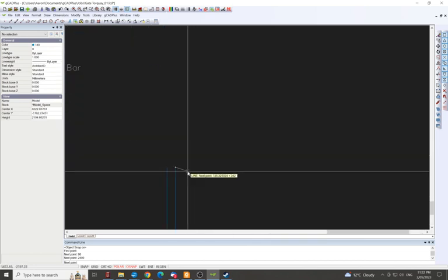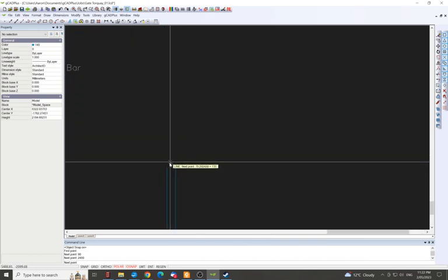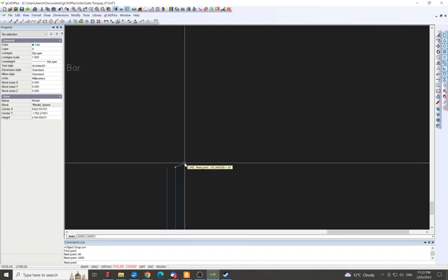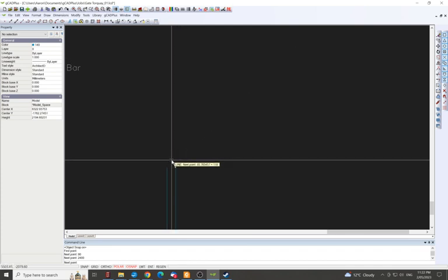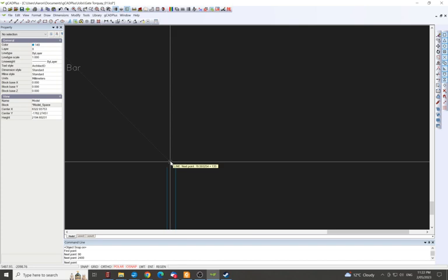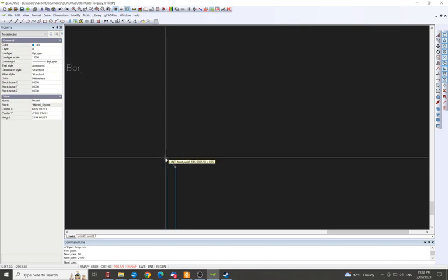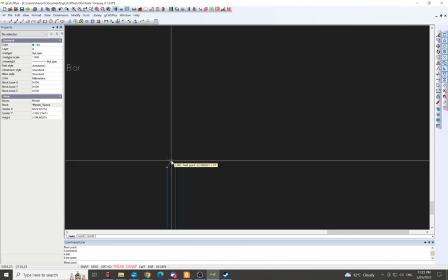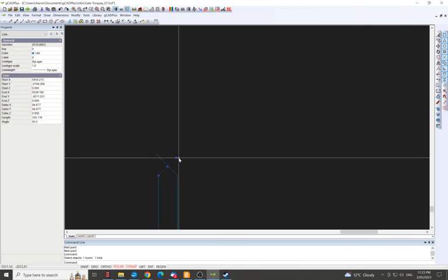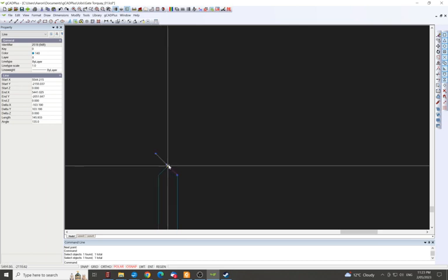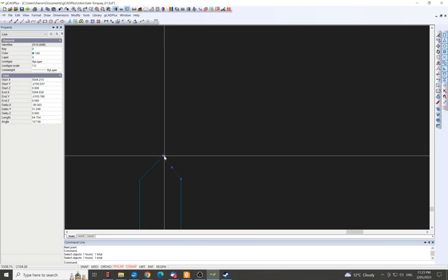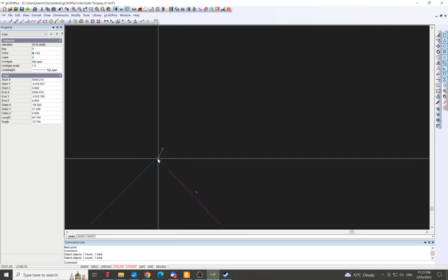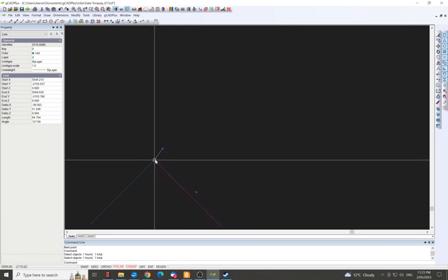Alright, and then we can lock on a 45. We've got 135 there, so the other side is 45 there, and then that's 135. And then we're not even going to put a measure because I don't know what it'll be. It'll probably be about 45 mil, but we're just going to overrun it. And that, snap to there. Highlight it, bring it back to the end. You can trim it, the trim tools are there. You can learn how to use it, but I'm just going to do this for now. Oh, I made a bit of a mistake. Make sure this snaps onto the end. There.